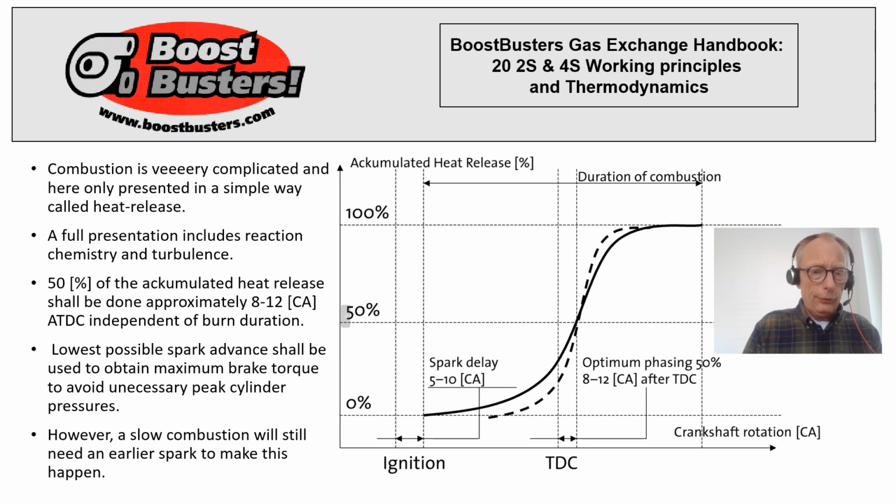Combustion. Combustion is maybe the most important of all systems, independently of how interested you are in gas exchange and charging systems. Combustion can be made very, very complicated, but I choose to do it as simply as possible. So I'm neglecting combustion chemistry, for instance, and how turbulence is created, and I try to explain the combustion with something called a heat release, or even an accumulated heat release.